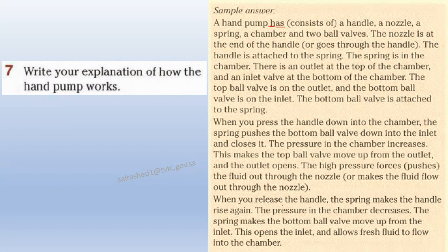To release, stop holding the handle. The spring makes the handle rise. The pressure in the chamber decreases. The spring makes the bottom valve move from the inlet. This opens the inlet and allows the fluid to flow into the chamber.